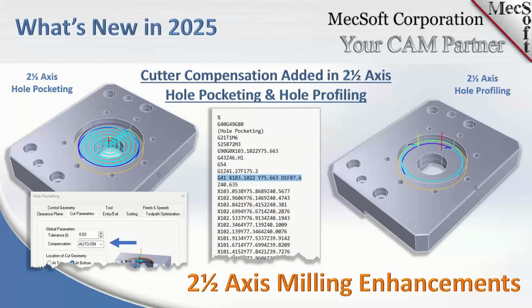You can get very tight tolerances, like a press fit or a loose fit, say for a bearing or a sleeve. This is the method you want to use. And now that we've added cutter compensation, it makes it even better if you're cutting production holes or want to use the compensation feature in your controller.